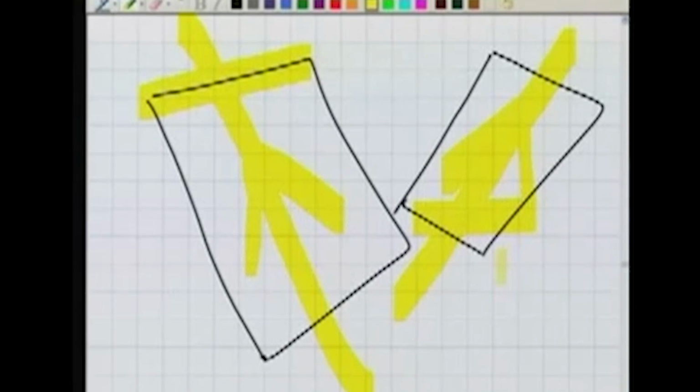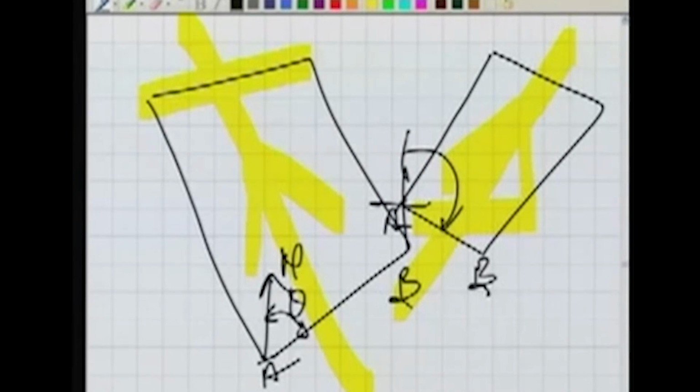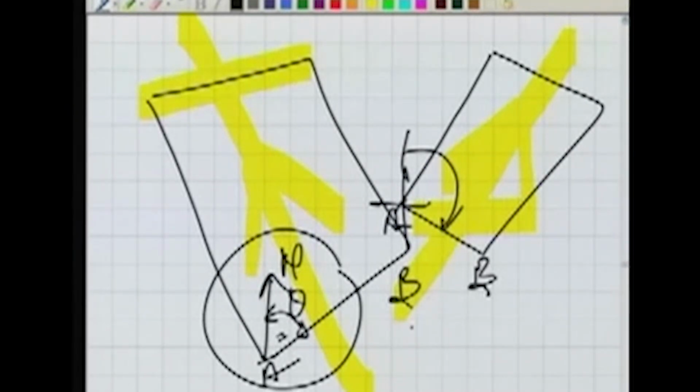How to eliminate this orientation error? We need to take the bearing of the lines also. Let's say I had measured the bearing of this line from the north, whatever this value theta is, and then I would have ensured that the same bearing of this line AB is maintained, because these two bearings are not the same. So by measuring this bearing and using that while we are plotting, we can eliminate this orientation error.